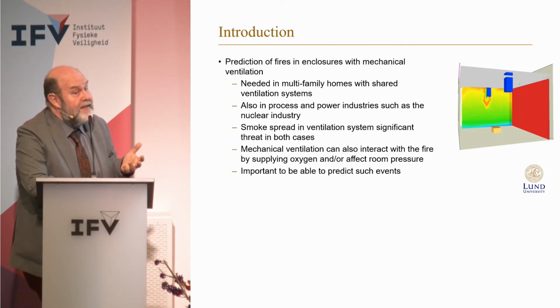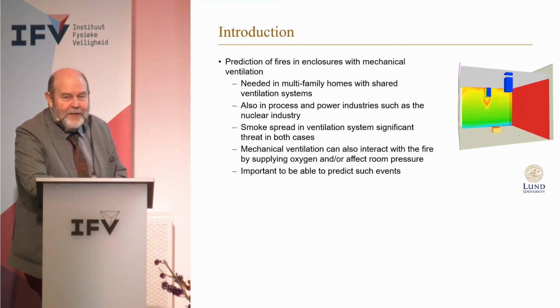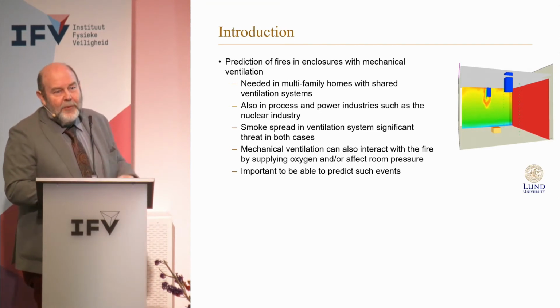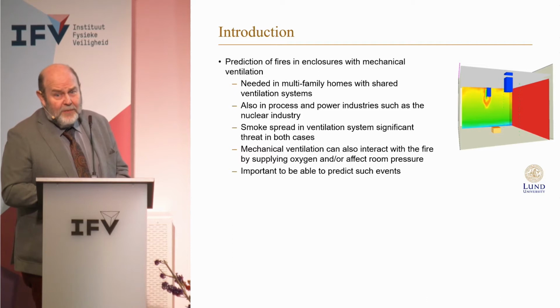And you feel that sometimes these days in certain office rooms or public rooms that this ventilation is important, because if we don't have enough oxygen, we will not work as well, we get a bit tired, a bit sleepy, and so on. So this mechanical ventilation should be enough. If we talk about residential housing and so on, these systems are quite complex. They are sometimes shared over different compartments, all depending on the regulation. Maybe one apartment is a single fire compartment, and then you don't want to have spread through the ventilation system. And you have a whole bunch of testing to be done, but you also have to check if that works. And there's a lot of technology on how to solve that.